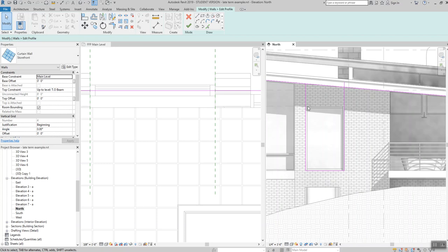So I've gotten now kind of the shape of it created, but it's a little messy, right? I have all this junk over here that needs to go away. So I'm going to come up here to trim. Click, click, click, click, click, and I trimmed it to the shape that it needed to be. Escape, escape.